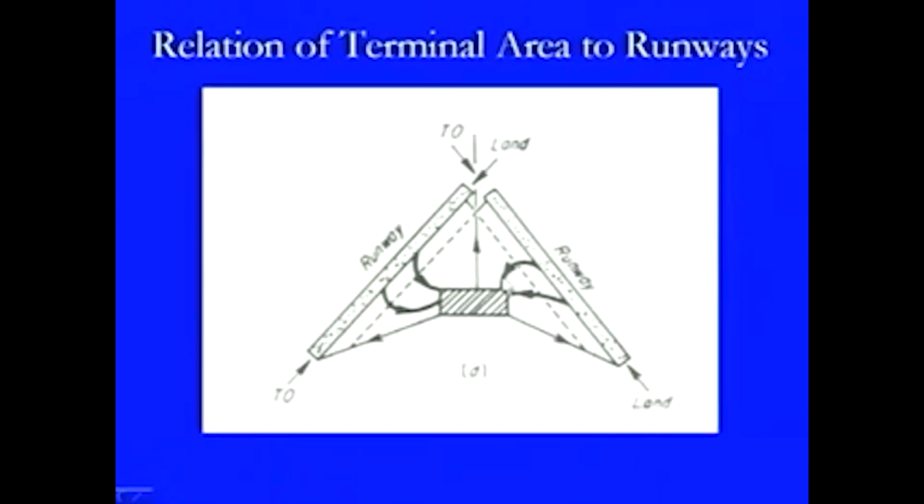So, it is an opposite condition for both, because if the takeoff on this runway strip is in this direction and again there is a takeoff in this direction, then both the runway strips cannot be used simultaneously, because there are all chances that in the flight path in the airspace there can be a collision. So, that is the reason why we are having the movements in opposite forms. And again what we can see is that there are unidirectional movements being shown along the exit taxiways, or the parallel taxiways have been shown by the dotted lines.